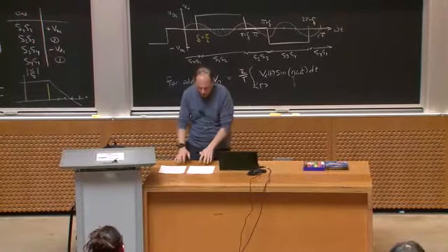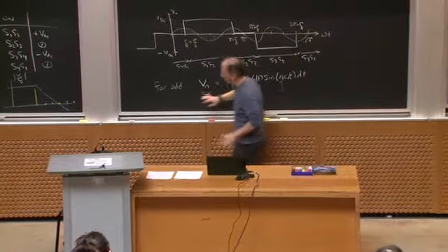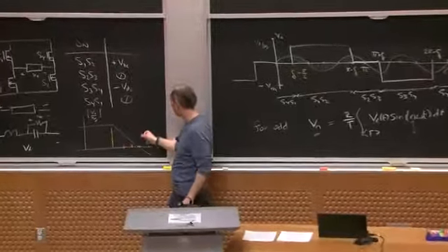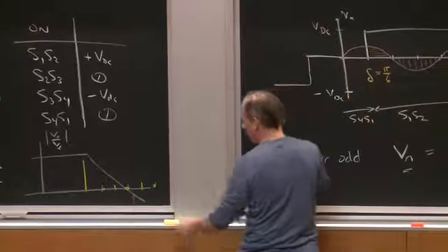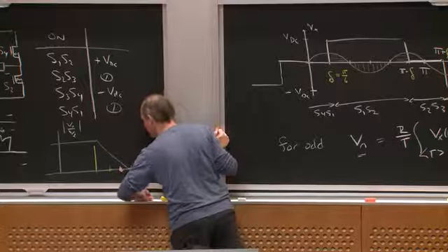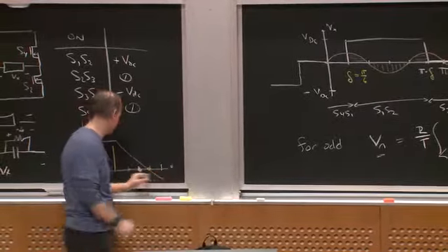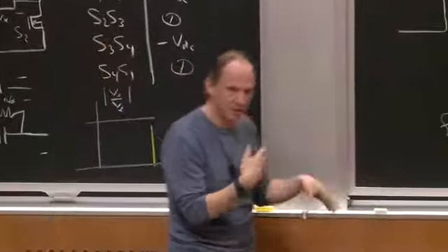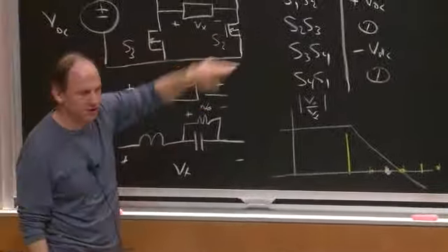Okay, so how might I go about it? Well, a principal reason I did this was because I said, okay, I've gotten rid of the even harmonics, but I've still got to worry about 3, 5, 7, etc., right? If I picked my angle just this way, I would pin 3 to 0. So that would kill the third harmonic, okay? And since the fourth is gone by symmetry, the lowest I have to deal with is fifth. Now I'm starting to get some nice space here, and that lets me get much more pure filtered waveforms at the output compared to this kind of pulsy shape I'm generating.